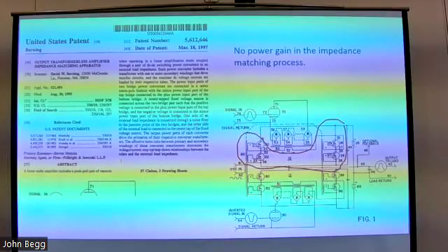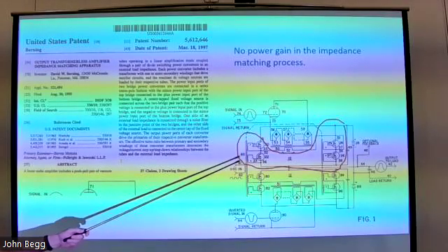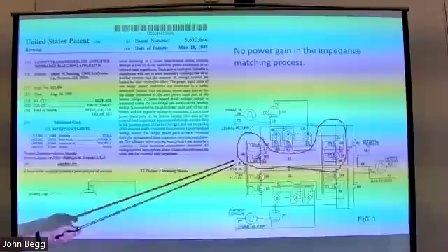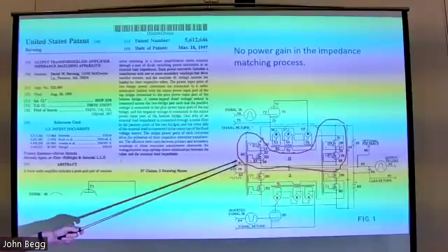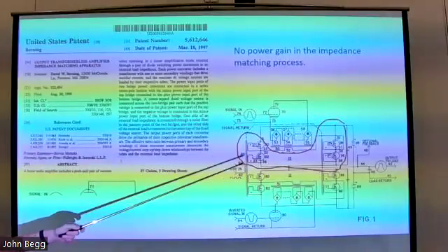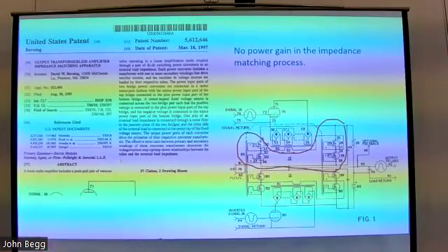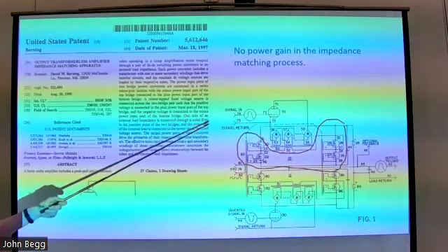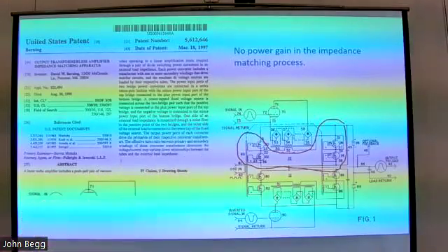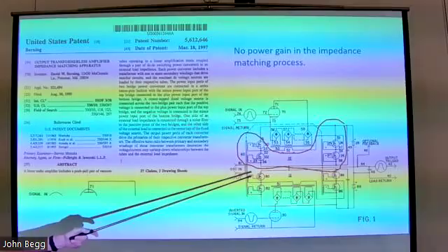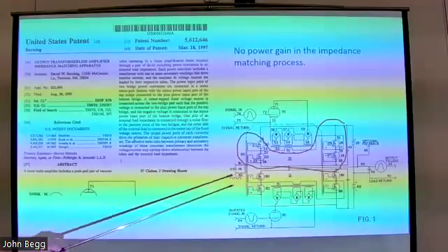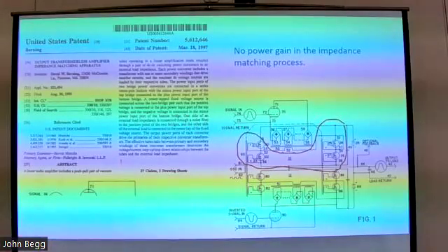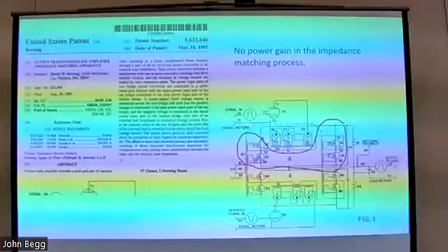I won't say any more of that, but this is the fundamental circuit for half of it. This is like the positive half, and this is the negative half. The inverted signal through its tube drives this half, and the non-inverted signal through that tube drives that half. And then the two are combined to drive the load, which is a speaker. Next slide.